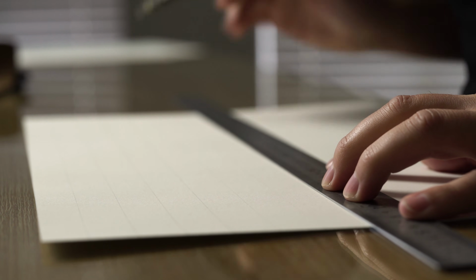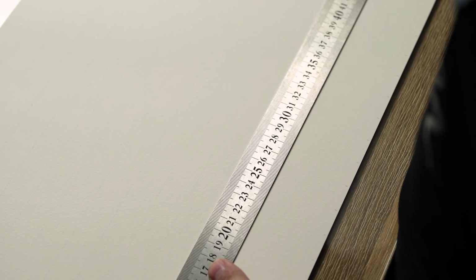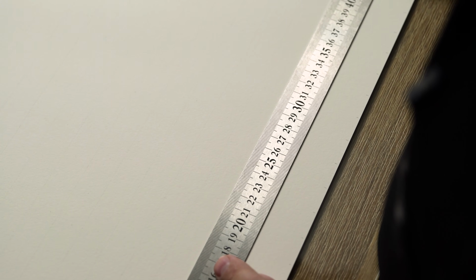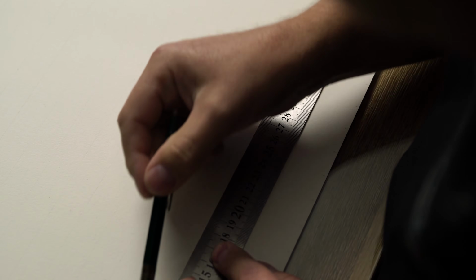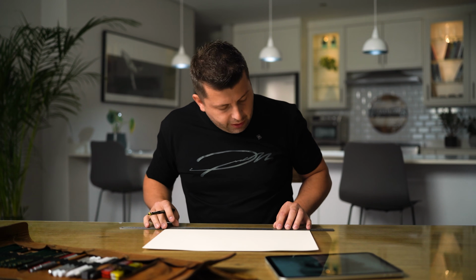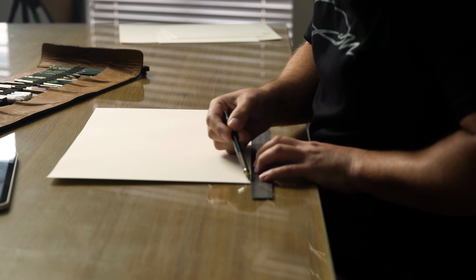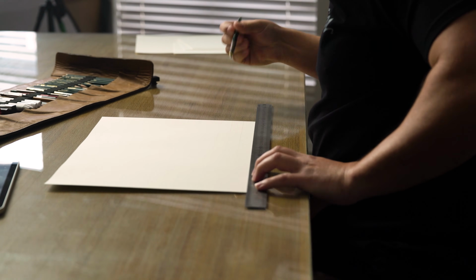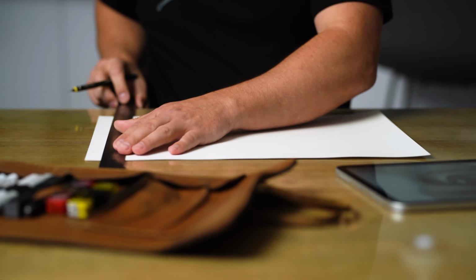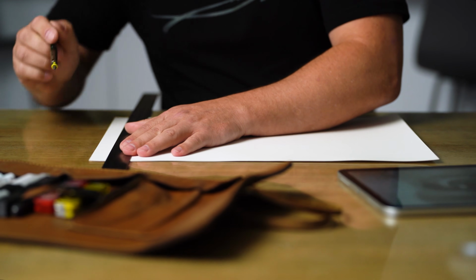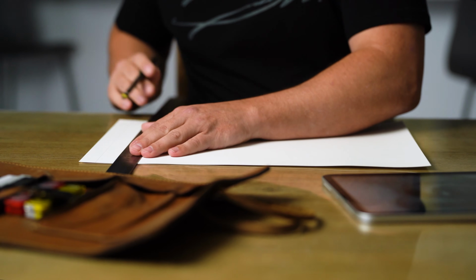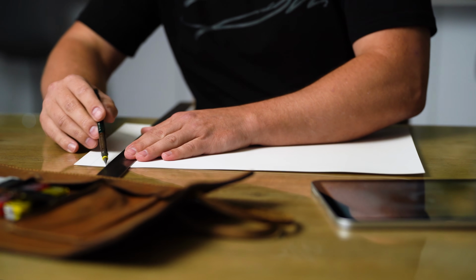You want to make sure that you use very little pressure when pulling these lines. They must be barely visible, just enough for you to follow. When I pull my lines, I love using my 0.35mm mechanical pencil with a 2B lead. That just ensures that my line width is extremely thin and very light. Okay, now let's pull our vertical lines. This is not the funnest part of drawing, but it is very important because it's going to help you a lot with the accuracy of your work.